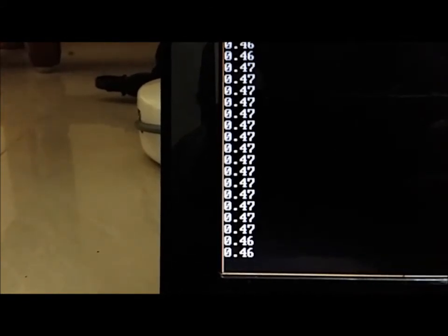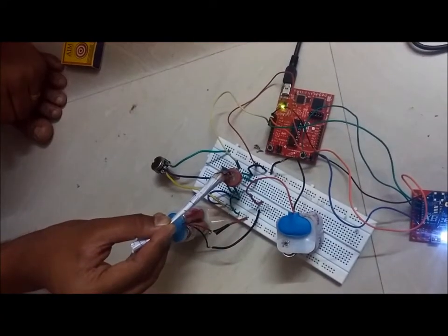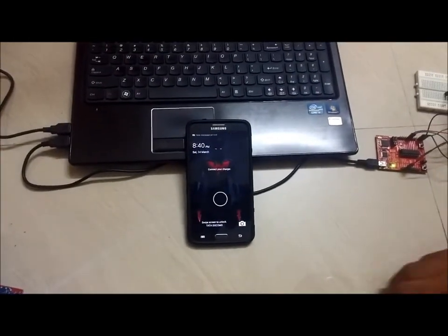We now burn a piece of paper near the carbon monoxide sensor to increase the concentration of carbon monoxide. Due to the increased concentration of carbon monoxide near the sensor, the values observed in the serial monitor are continuously increasing. When the values increase above a voltage of 1.5 volts, the master instructs the GSM module SIM300 to send an SMS to the fire station alerting them about the possibility of a fire.